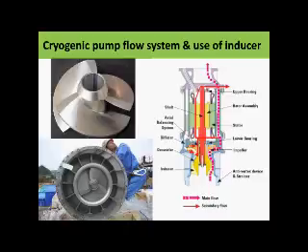So the main flow, you can see, is going like that, induced centrifugally by the impeller, going from the side and going through the discharge. But a secondary flow is also created, and that secondary flow is not only cooling down this part, but also lubricating the bearings, the top bearing and the bottom bearing, and of course the flow also goes out with the main stream of the flow.